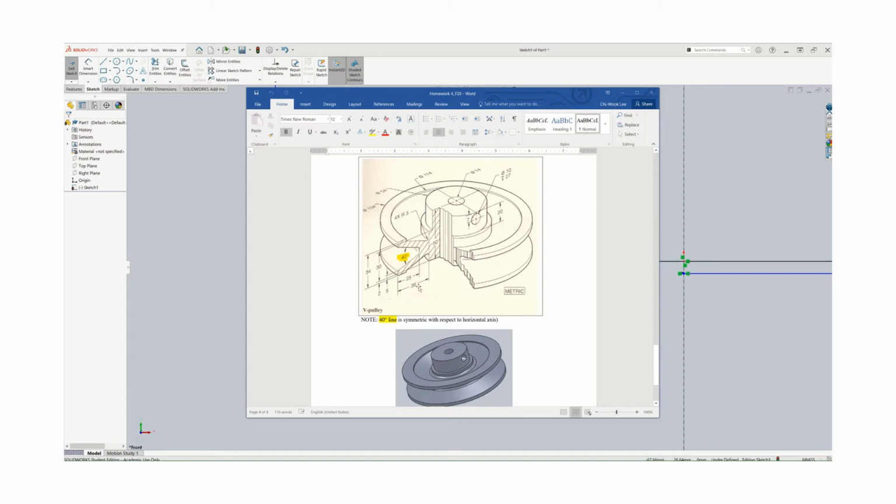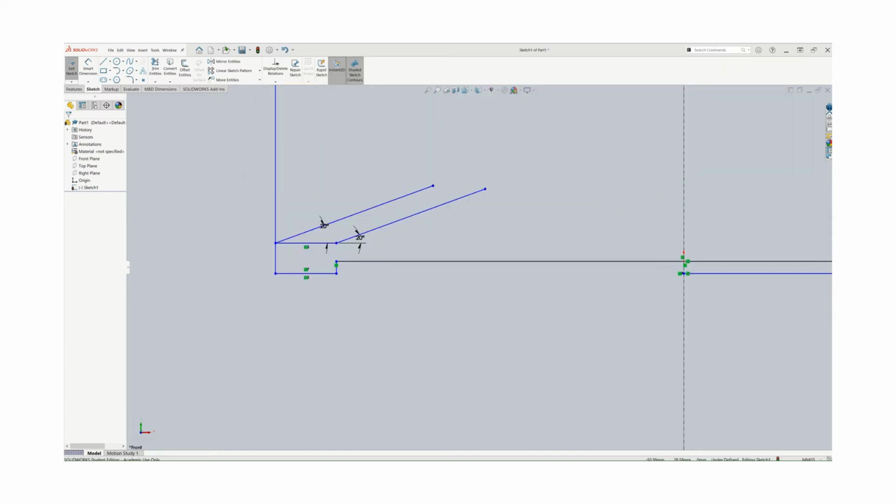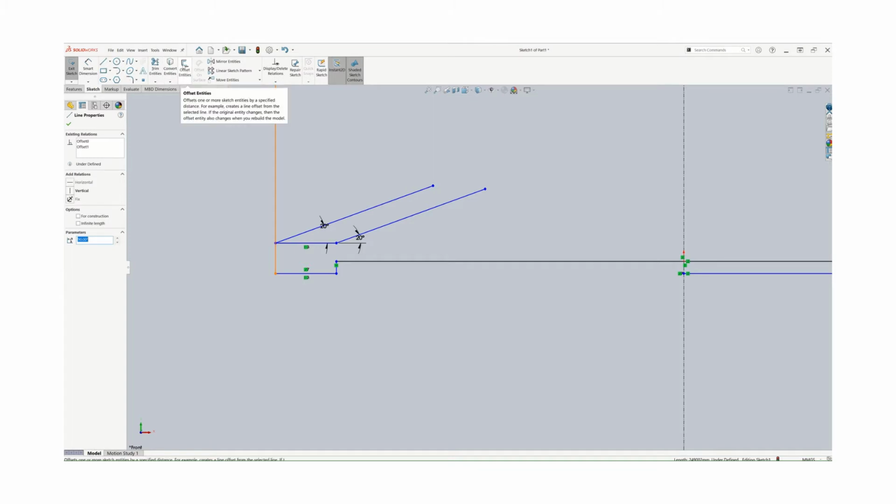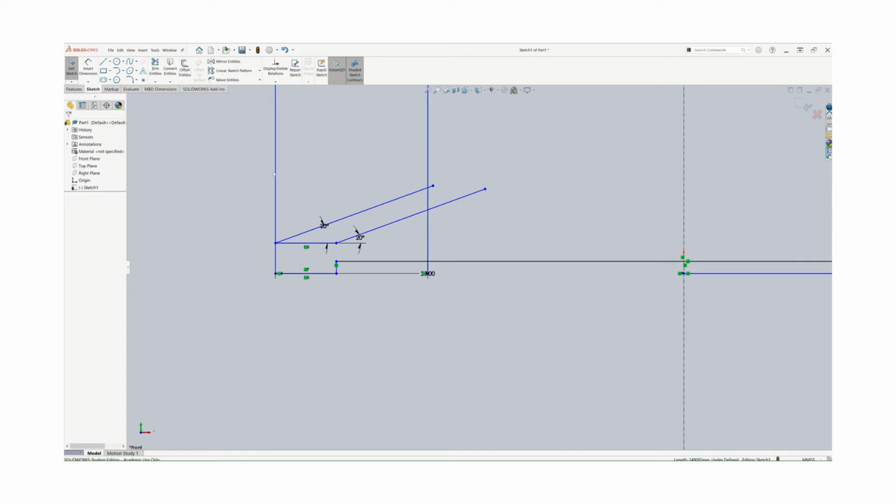And then if you look at the bottom corner here, I have the 125 millimeters offset and 36 millimeters offset from the leftmost edge, so I will draw a vertical offset for that line. I will offset this line, because that's why I didn't delete that one or trim those things, offset by 25. So in this case, I'll have 25, in the right direction. I just click on it. And also I will offset the same line by 36 millimeters, and that's what I need.